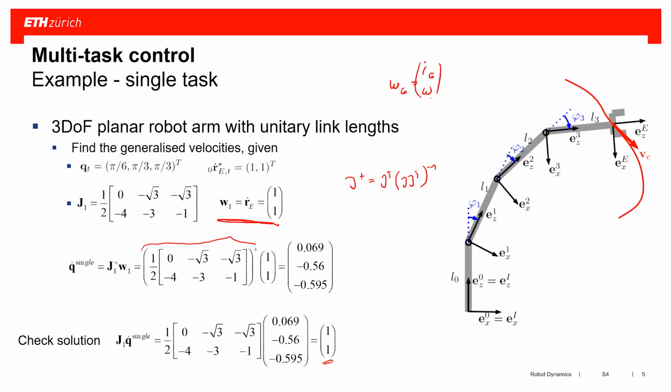So there were some more questions related to the pseudo inversion. Let me do the following: I will post a link on Piazza related to the different pseudo inversions that exist, for systems which are column rank deficient and systems that are row rank deficient. The difference is, in essence, if you have something which has fewer degrees of freedom than what you want to achieve, you have to find the solution which gets closest. So you have to find the q dots which get closest to the solution.